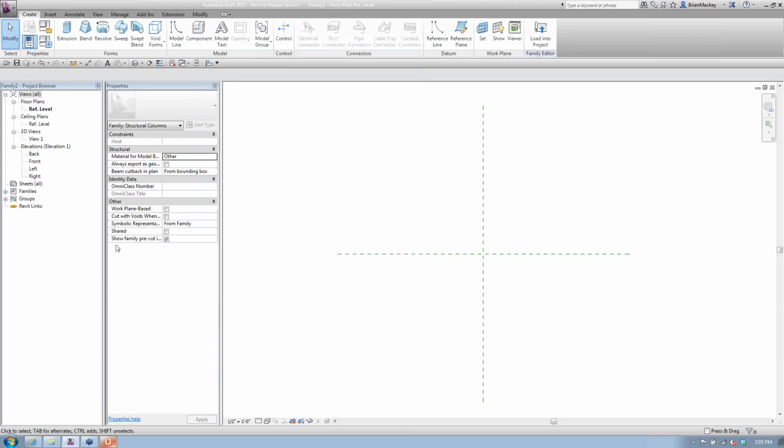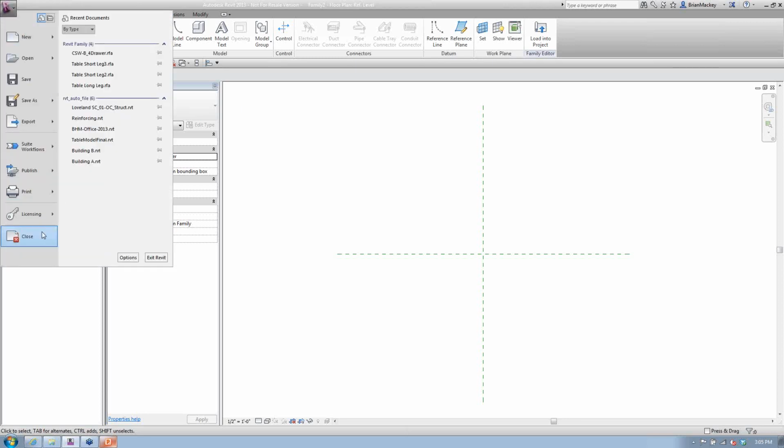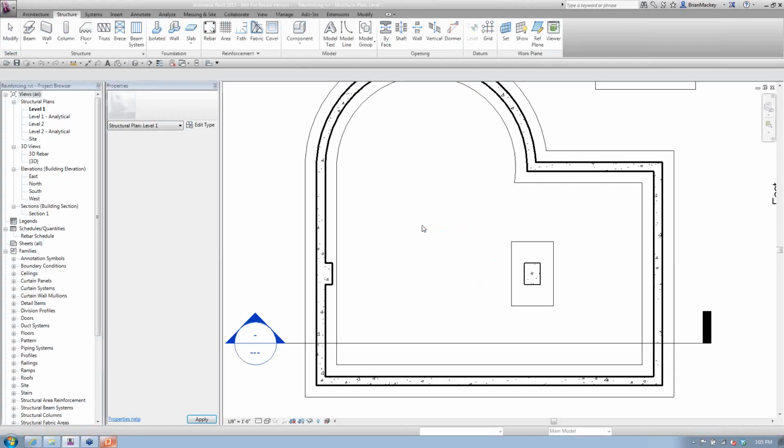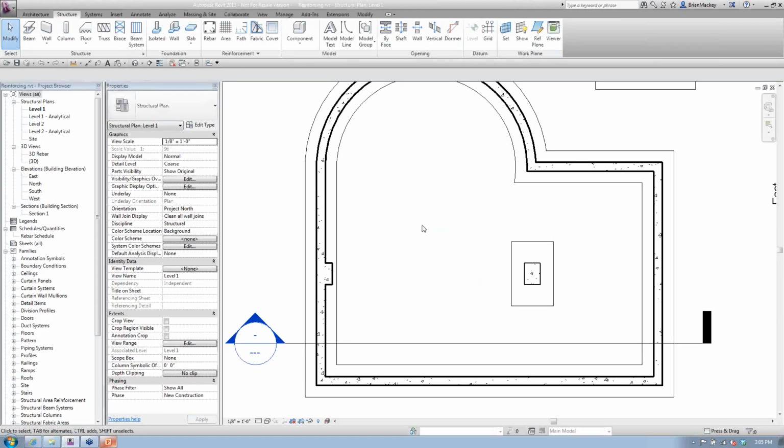That in your family, there's a checkbox that says allows reinforcing. So when you start going and creating some of these families, if you want it to be able to be reinforced, you can check the allows reinforcing, or you can uncheck that depending if you don't want to. So like slab edges can allow for reinforcing, they don't have to. And there's some other families, and I just drew a mind blank on what that family is going to be, that will allow you to have that property as well. So just want to put that out there. If you start grabbing something, man, this really shouldn't allow for reinforcing, it's just simply because that's checked in the family type properties. So wanted to point that out.